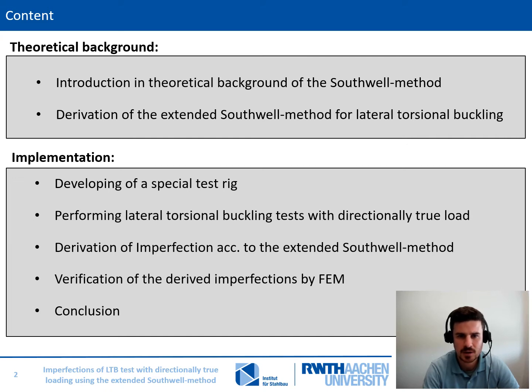My former colleague Matthias Wischolek has developed a special test rig to perform lateral torsional buckling tests with directionally true loading. With the performed tests, we can then derive imperfection values by using the extended Southwell method. We then finally check these imperfections by using numerical investigations.